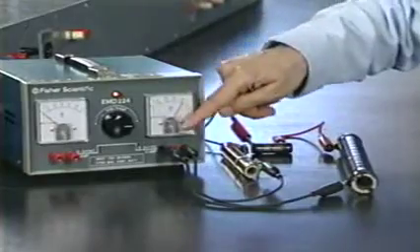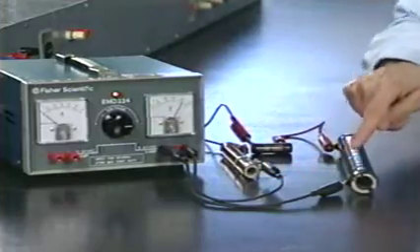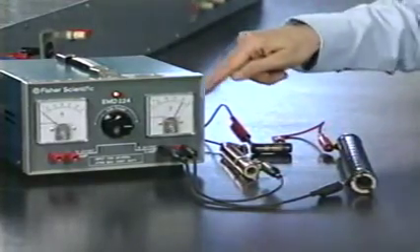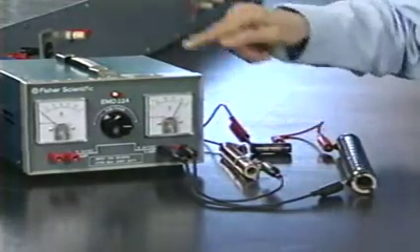The second rule concerning series circuits is that the total resistance is the sum of the individual resistances. A simple way to express this rule is to say that resistance adds or accumulates in a series circuit. Since a series circuit contains only one path for current flow, the current is hindered by each resistive element in the circuit.